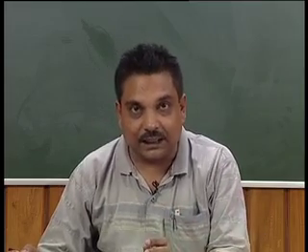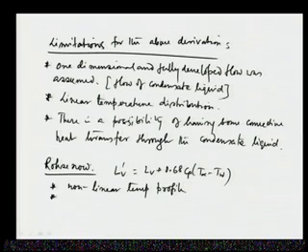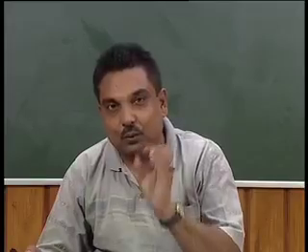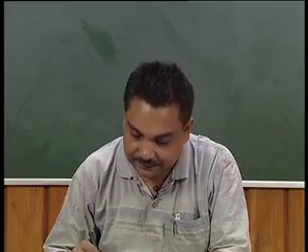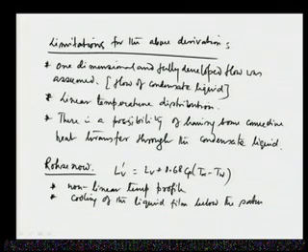In the above equation for h bar, if we replace L_V by L_V dashed, it takes care of two things. One is a nonlinear temperature profile, and the second is that the film is cooled below the saturation temperature, that is, cooling of the liquid film below the saturation temperature.